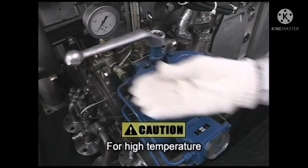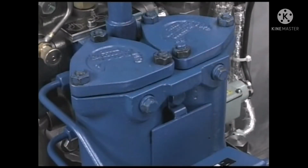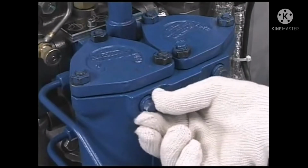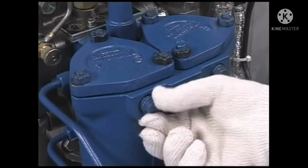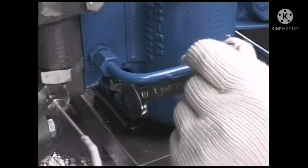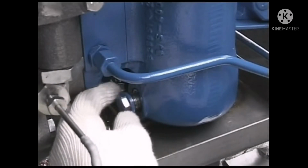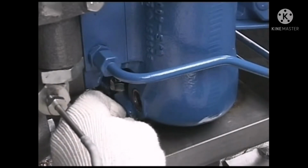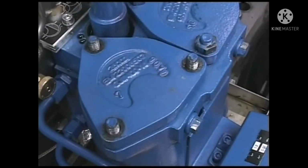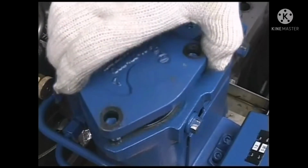First, shift the changeover lever to the disassembly position and open the air bleed plug. Open the drain plug and drain the fuel oil. Remove the bolts and cover and pull out the element.